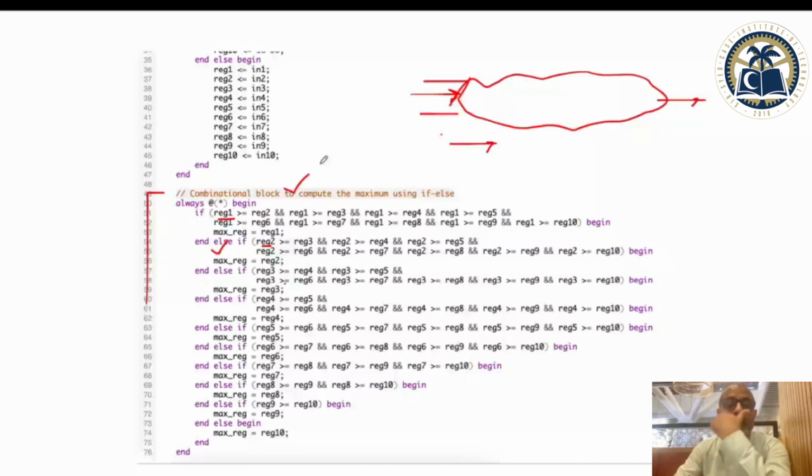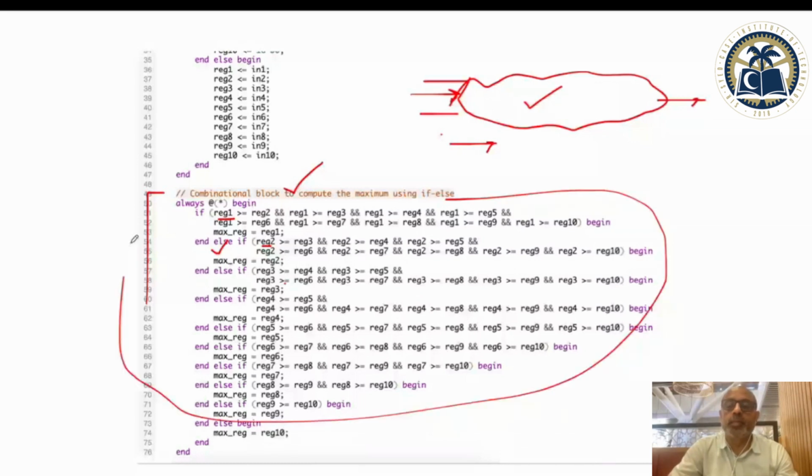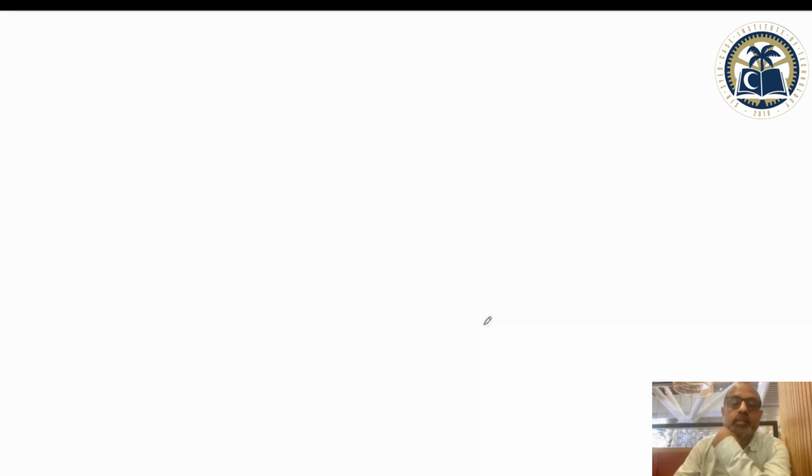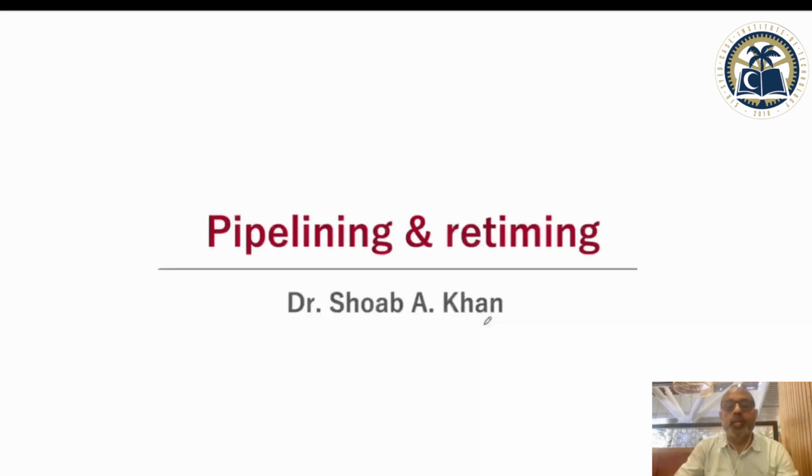And so today, again, as I mentioned earlier, we are going to see what if we have all these comparators, and how many comparators are going to be there. There are many, like you can perhaps count, and the synthesis tool may be able to optimize the combinational logic. So definitely, it will try to optimize the logic. And as I mentioned earlier, you really don't care how this gets inferred or implemented. All you know is that this is a cloud which is going to give me an output value, but you are making this cloud very big, and it is going to have a lot of delay. So one thing to handle such a situation is that you pipeline your design.